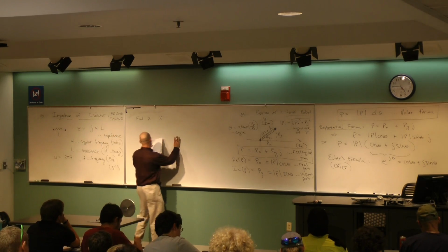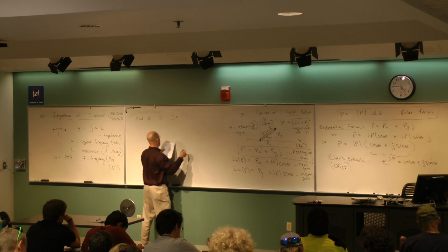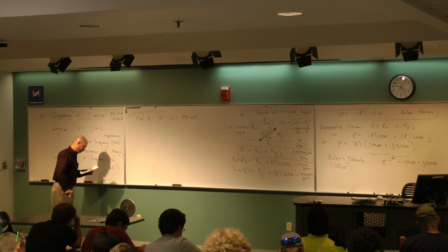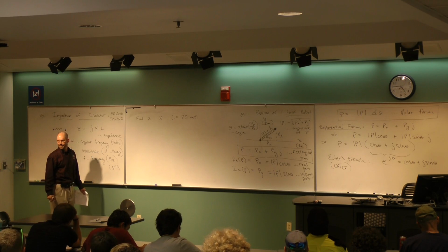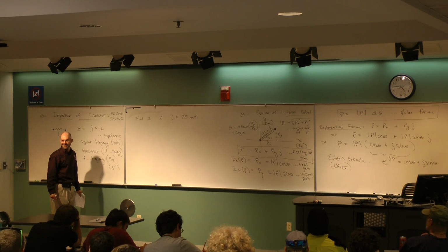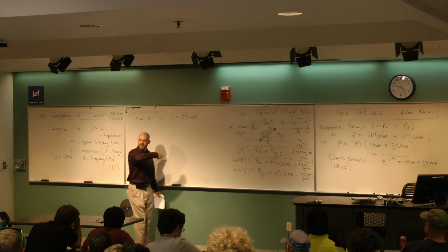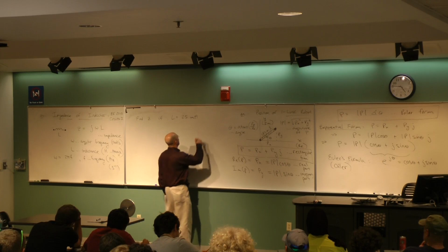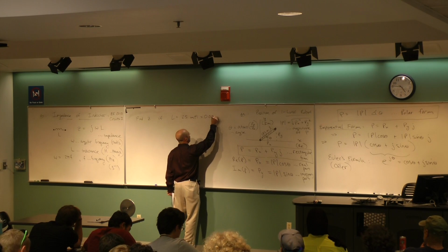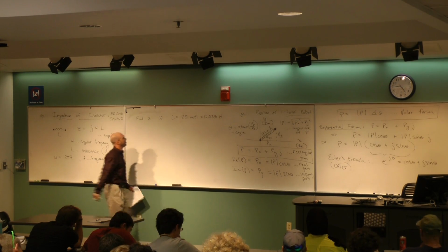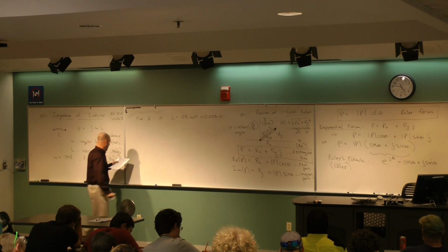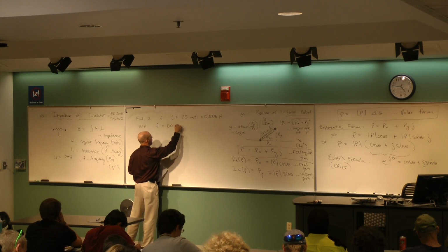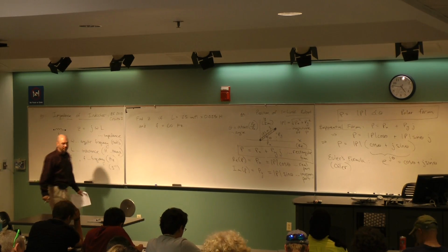So find Z if L is equal to 25 millihenries. What's a millihenry? Milli, like a millimeter, means what? Times 10 to the -3, divide by 1,000. So you might as well just cut to the chase and write it as 0.025 H. So it's 25 millihenries, and f is equal to 60 hertz, right? So we'll talk about a real life wall outlet.